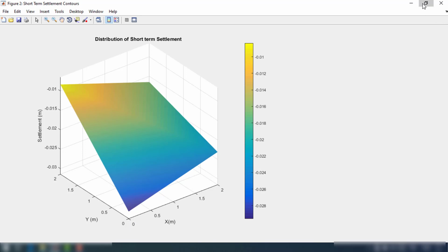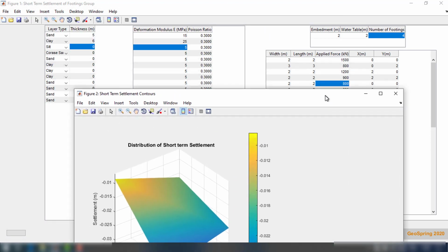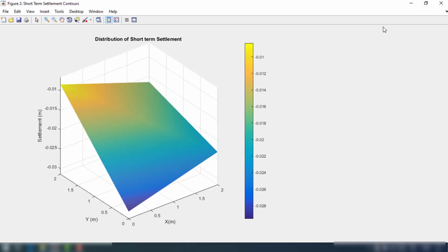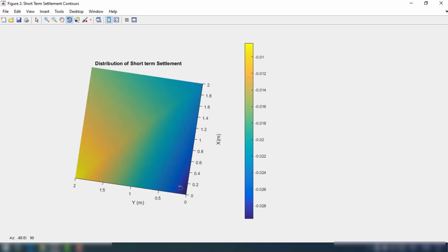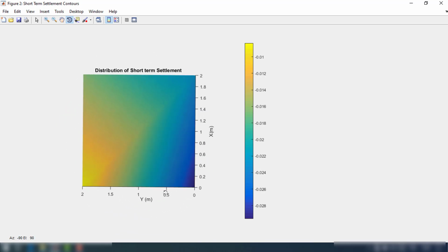Okay, so actually geotechnical engineers would like to see the 2D distribution. It's more practical for them. So here we have the coordinates and the settlement distribution. So the most important value, it's about 2.8 centimeter, 2.9, and here you have just 1 millimeter. You can actually add,